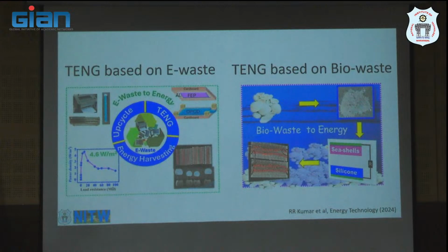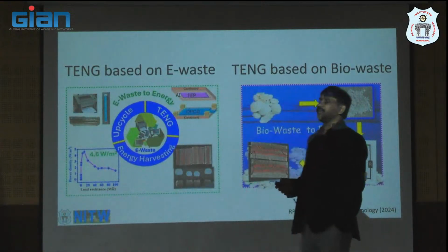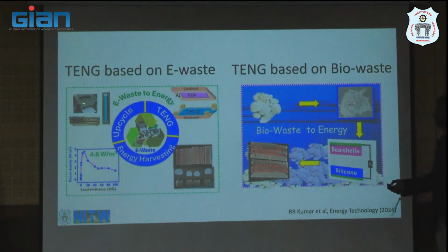If you look at this Canon LBP 2900 model cartridge, most of them will be thrown away once you refill it 3-4 times and it doesn't work properly. But if you open it carefully, there is an OPC drum, which is blue in color, a charge storing layer in the printer where ink is attached. Ink particles will be attached here and go to print on the paper. This is actually an aluminum tube which is coated with some polymer layer.